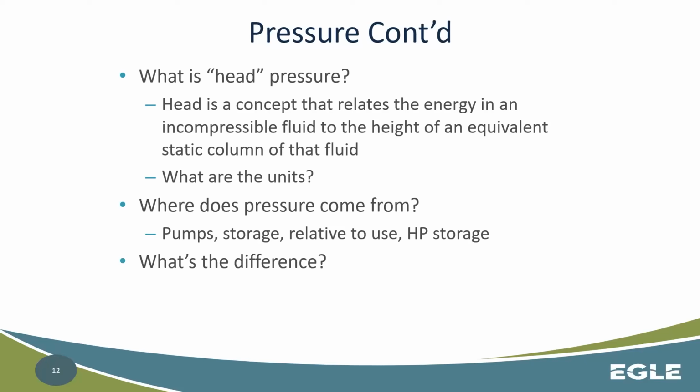A pump is used to create flow, and if you resist flow, it produces pressure. So as I flow water through a pump into a pipe and the flow starts to slow down, it starts to build pressure. I can continue packing and packing more water, and it builds up that pressure. In storage, we have pressure associated with it because gravity is exerting a force on that body of water.